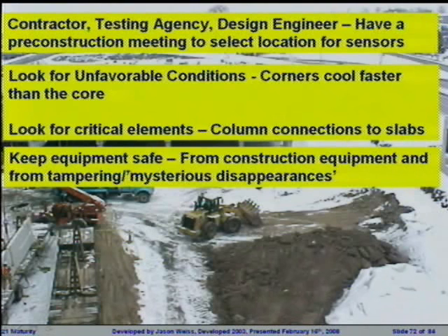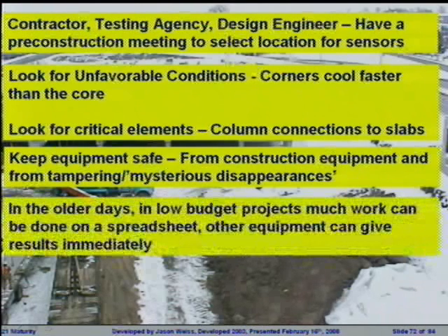The other thing is these tend to attract construction equipment. So what you'll find out is you want to keep this out of the path of construction equipment. I can give you an example if you would like to see one of these data loggers that decided to battle it out with a 20-ton dump truck. The dump truck won, in case that was a question. It beat up on the little computer chips that were inside of these data loggers. So you want to make sure that they're tamper-proof, out of the way, so that they're not in anybody else's way.